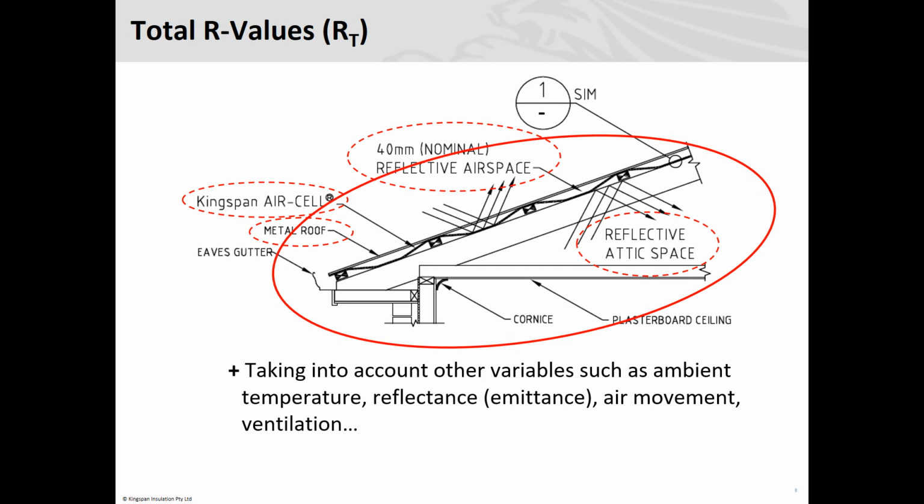Yeah, okay, yep. So we'll talk about the K values. Yep, R value I'm talking about. Yes, so to get an R value, everything that's got a K value, you've got to divide that by its thickness. So yeah, we will go into that.